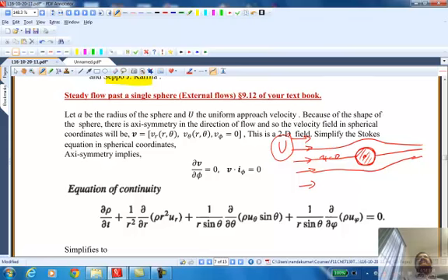Only laminar flow, called creeping flow, low Reynolds number flow. Reynolds number going to zero. The solution that I'm going to obtain after a lot of hard work, and this was done by Stokes almost 150 years ago, is going to be valid only up to a Reynolds number of 1. If the Reynolds number is greater than 1, that solution will not be valid. Later on, people have improved it through series expansion. We will see some of those ideas as well.